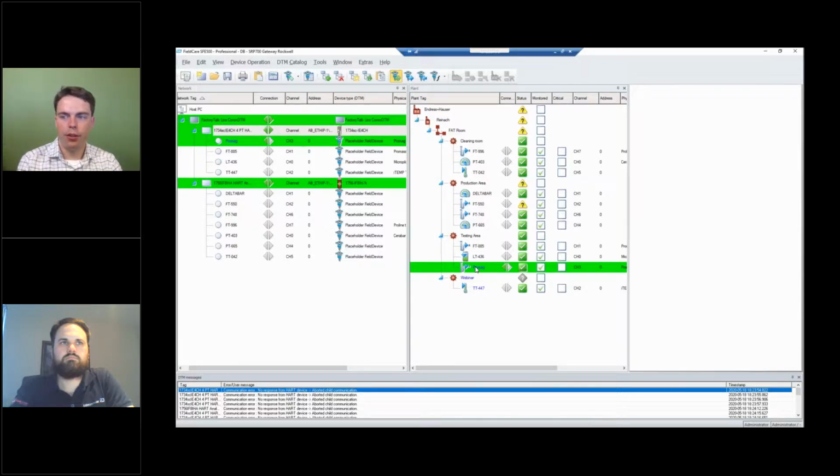So with our technology, if we even put in these HART modem channels before the IO card, we can get it, strip the HART off. If we have Profibus, we can directly connect. If we have Ethernet IP or Profinet, we can also connect to this and then go to HART devices where the remote IO. And then it's very versatile. So you can have one tool fits all in combination with that tablet that you can even go to devices that are not connected to the network.